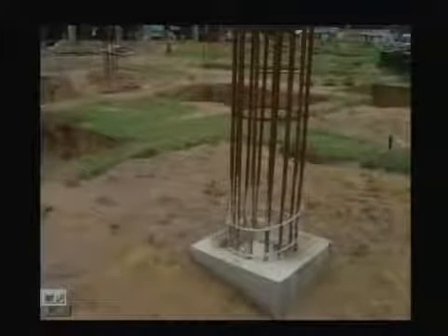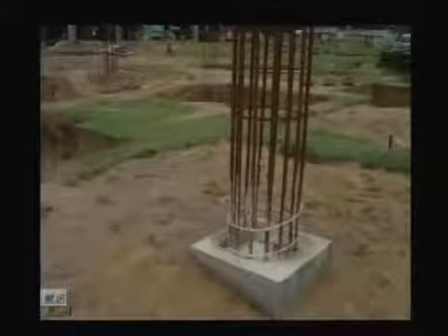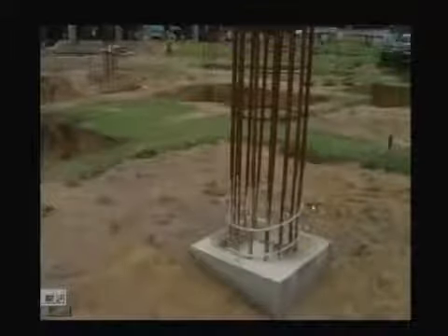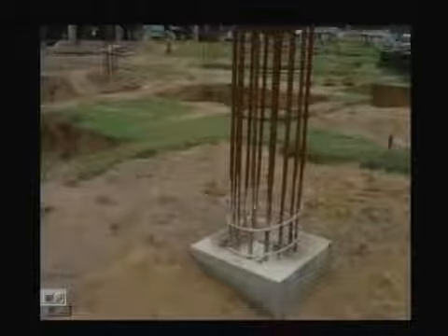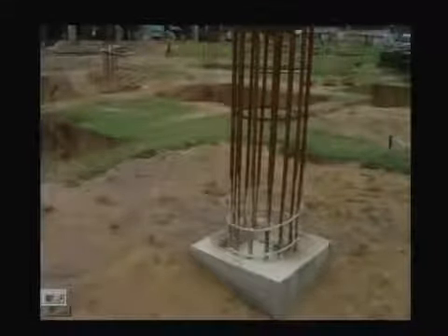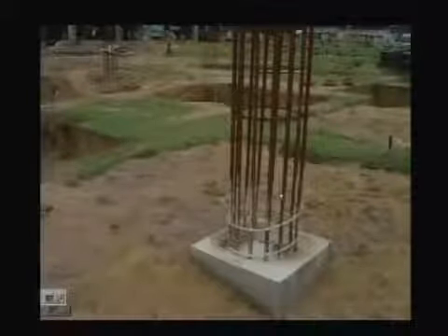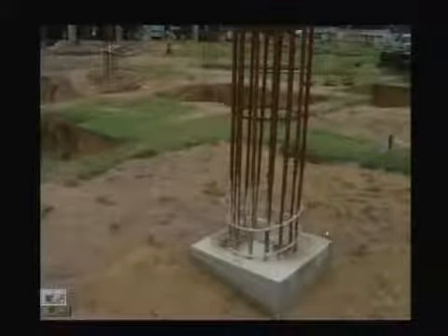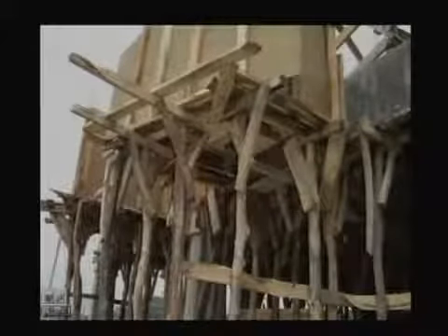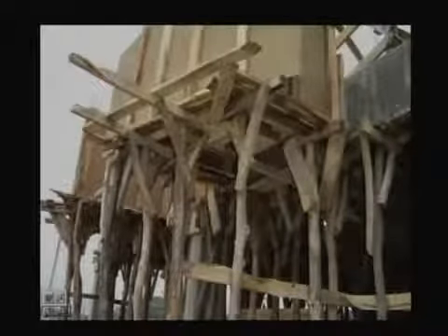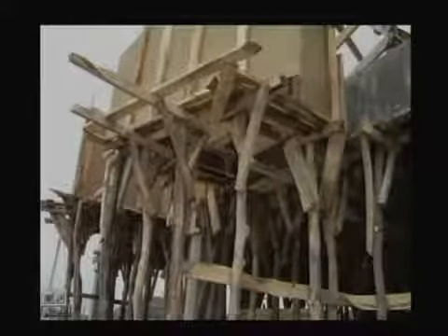This is your circular column, and here you can see that it has a spiral. The tie we are making is a spiral one. This is another type we generally make, and here they are going to construct a circular column. This is the base at the bottom, the footing. After this they will start the circular section. Obviously we have to use this type of arrangement, otherwise it is so heavy that everything will fall down.